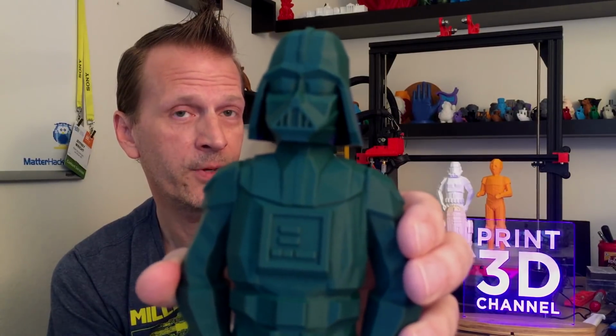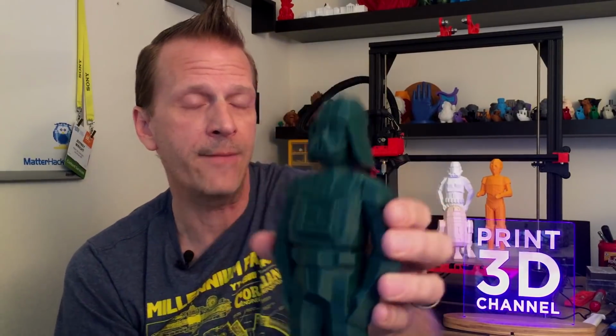Okay, so you saw my settings in Simplify 3D and the bit of hoop jumping that I had to go through to get good old Darth Vader here to print. But he looks really good and I'm really happy with the results. The problem I found, and I haven't glued them together yet, is that the hands, when they connected to the body, the geometry went inside of the geometry of the legs.